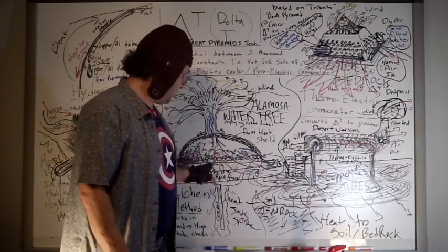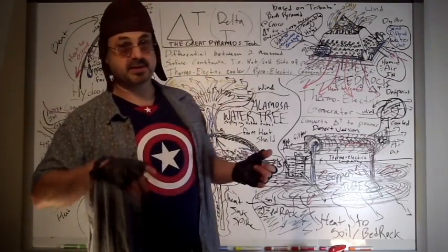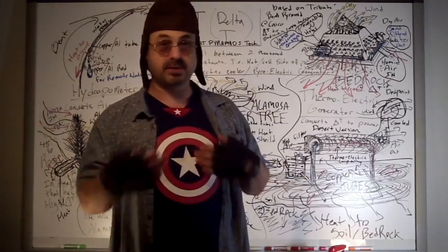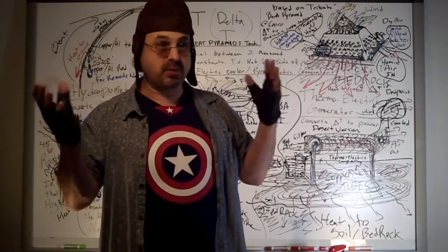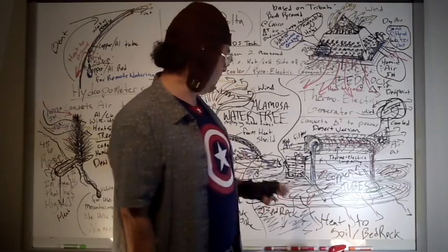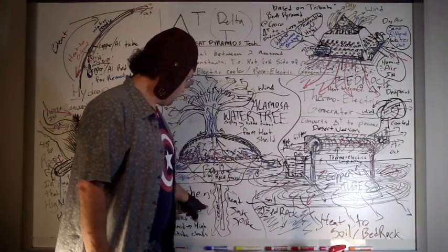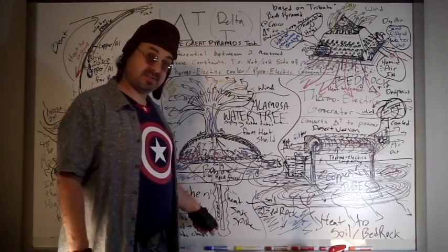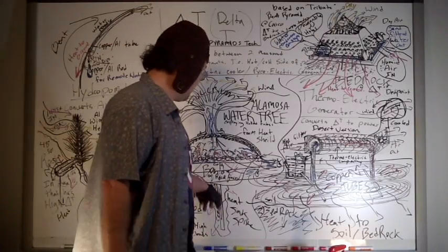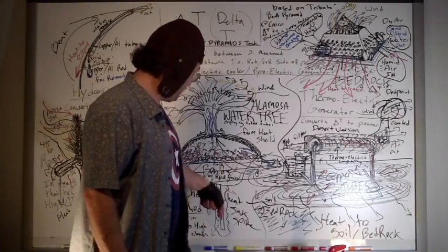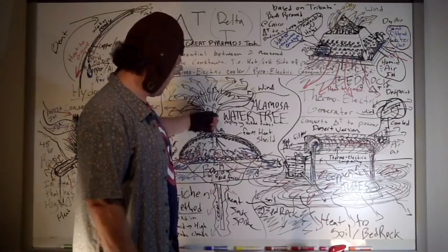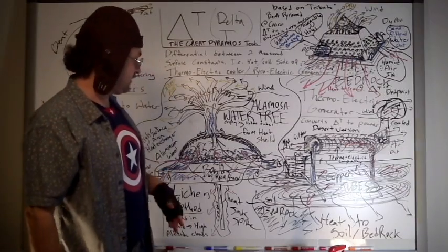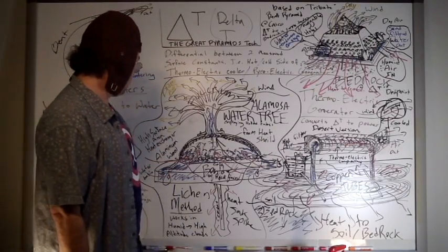So either way, you want that thermal conductivity of the aluminum, and you want the protection of a layer of copper or a layer of another metal that won't interfere too much with the thermal conductivity to the surrounding bedrock or soil. And of course you're going to want to use a cement of some kind, usually, I suppose. In this case, you don't necessarily have to. You probably just have to beat it into the ground with a giant spike hammer. Bang, bang, bang. Unless this is rock, then you have to drill it out and then set it with some epoxy or some thermal cement.